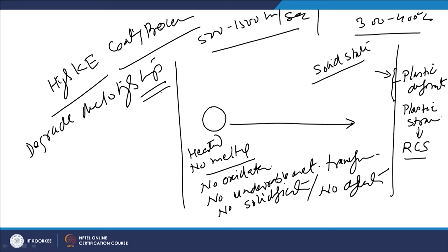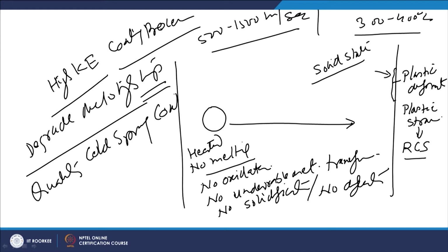And because of this, we find that the quality of the cold spray coatings is much better as compared to the other processes, as there is no melting, no oxidation, no undesirable metallurgical transformation, and no defects associated with solidification.